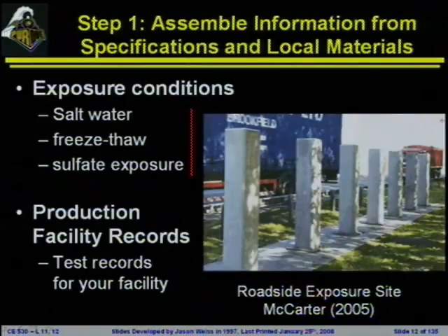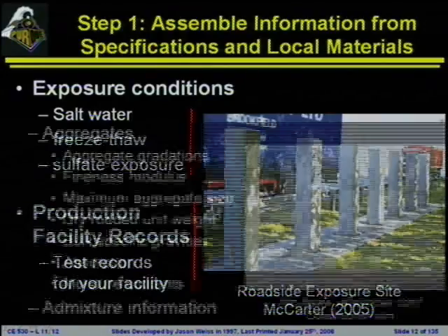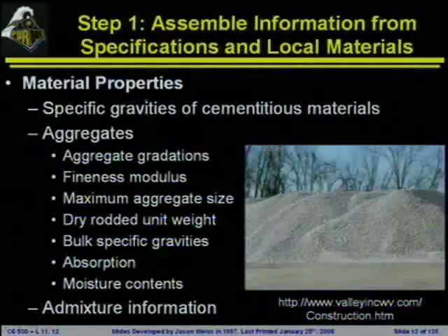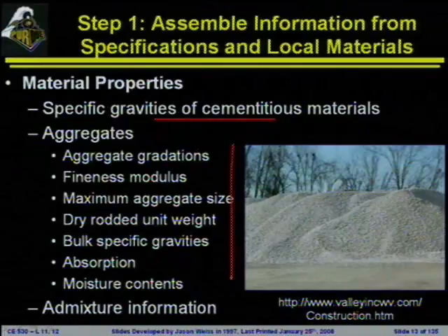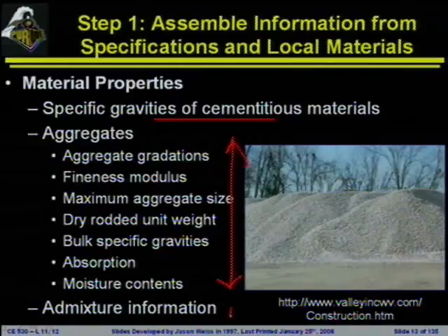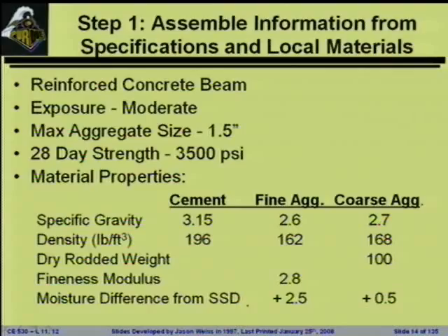You'll also need to have a little bit of information on how well you produce concrete. What's your track record? What's the consistency of the typical concretes that you make? We'll also need to generate quite a bit of information on the material properties, specific gravities of the different materials, a bunch of properties about the aggregates that we'll talk about, and what admixtures that we're going to need to have in order to make this concrete.